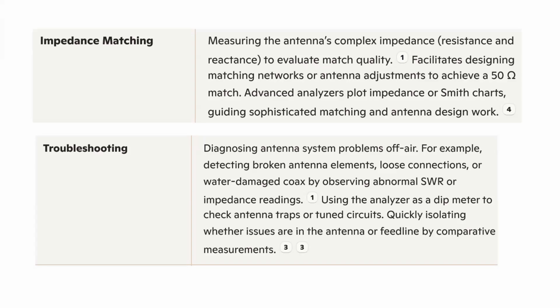But we all get into some kind of troubleshooting situation, and an analyzer will let you figure out those problems off the air and pick up maybe you have water damaged coax or a bad connector, adapter, and so forth.